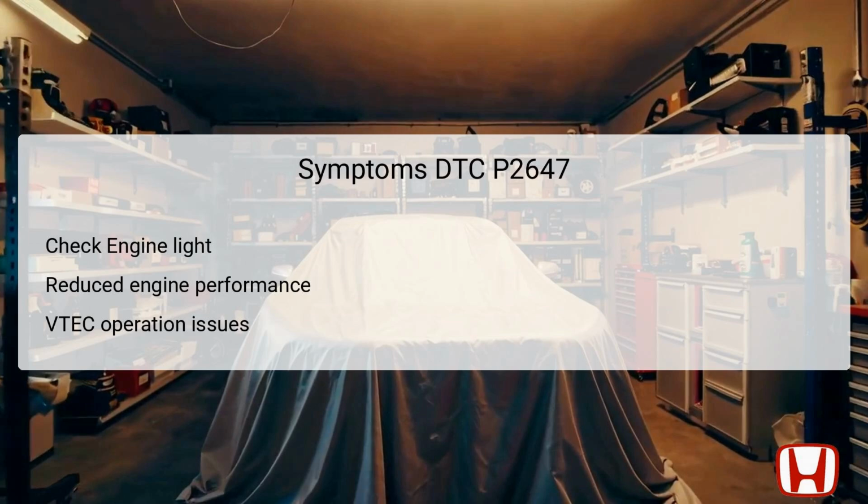DTC P2647 can manifest several symptoms that may impact the overall driving experience and performance of the Honda Accord. One of the most immediate indicators is the illumination of the check engine light, alerting the driver to a potential problem within the vehicle's engine management system. You may also experience reduced engine performance, which can be characterized by sluggish acceleration or unexpected engine misfires, particularly under load or during acceleration.